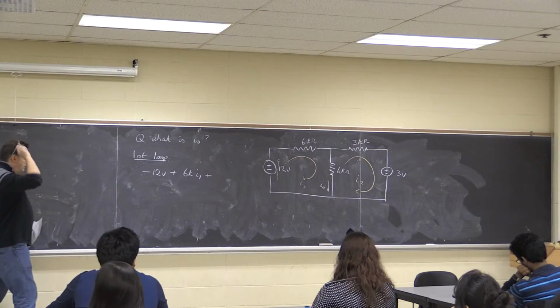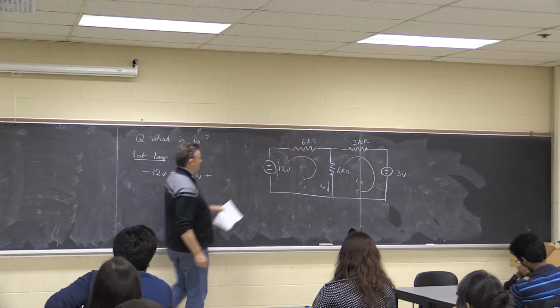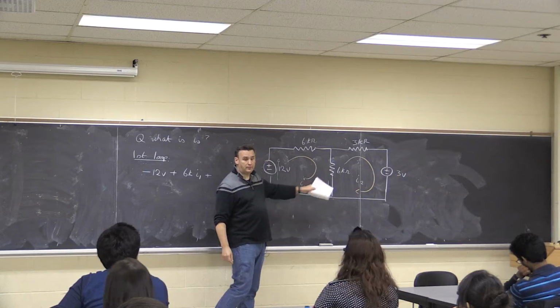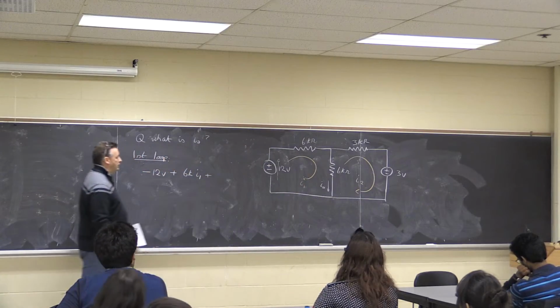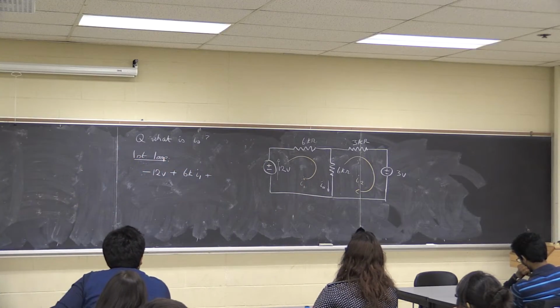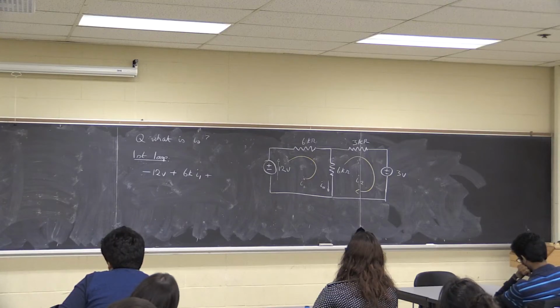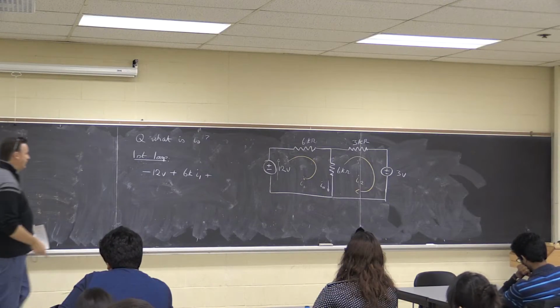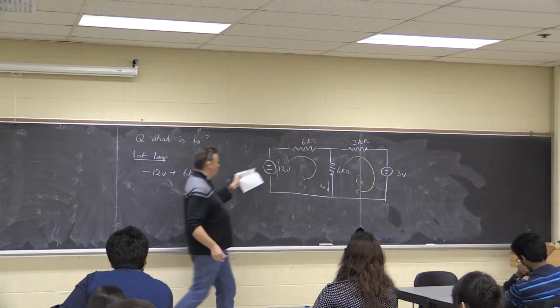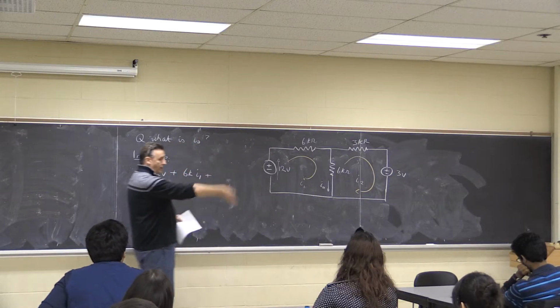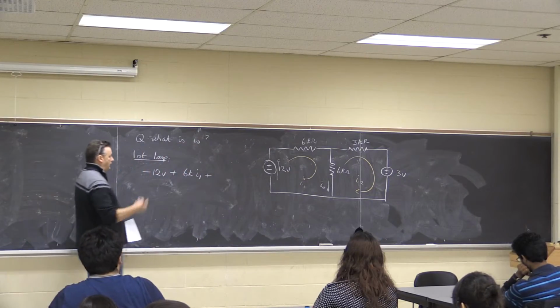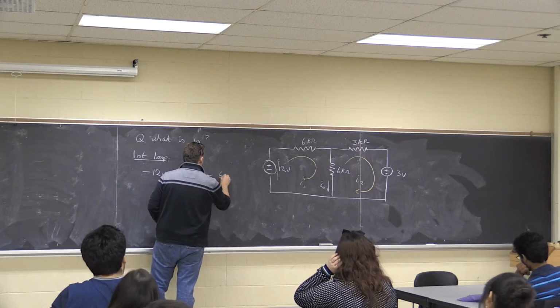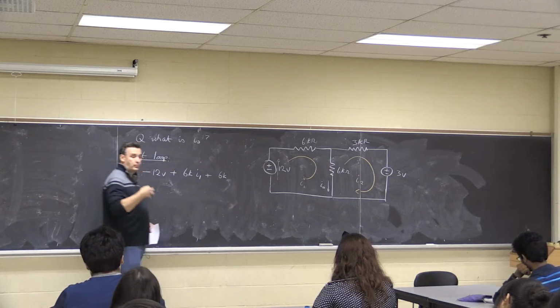Plus the voltage drop across this one. So again, I've got I1 flowing in the direction I'm walking around the loop, so I'm flowing with the current, so I'm sitting on an electron or a positive charge flowing around this loop, going in that direction. I go through the 6K resistor, so I'm going to have 6K, which is going to be the resistance.